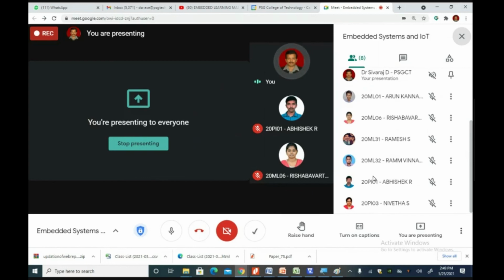Okay, so when you're being an electronics and communication engineer, if you are appointed in Robert Bosch and you are interested in making the display, which is called the instrument cluster, doing that instrument cluster, you are supposed to design a speedometer. Means you have to write a program by looking at the wheel speed sensor, and those wheel speed sensor inputs are given to the capture module. So whenever there is a transition, you have to capture that, and capture value 2 minus capture value 1, you will get the on time. So based on that, you are able to find out the frequency. Based on that, you are able to compute the speed of the vehicle, and then by doing the necessary code conversion, you can send it to the 7-segment display, because all the sophisticated digital displays in a car are also having only 7-segment display to display the speedometers, odometers, wherever there is a display. So this can be used in a more beautiful way. So thank you.